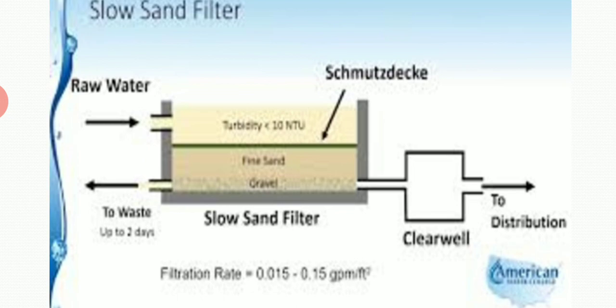After some time, in the uppermost layer of sand there exists a film of algae, bacteria, and protozoa, etc. When algae and protozoa start existing, the color changes and becomes green. That is the green line you can see. The impurity which is settling on the sand, we call the dirty skin, or sometimes the schmutzdecke, which acts as an extremely fine meshed straining mat.